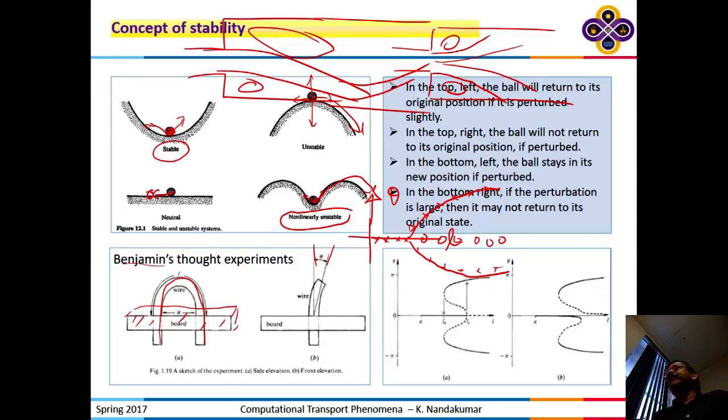What causes the disturbance in the expanding channel? Good question. What causes the disturbance to move the jet from being symmetric to non-symmetric? In an experiment, any slightest imperfections in the corner. Okay? If one corner is slightly blunt compared to the other one, that's enough to cause the flow to go to one side.